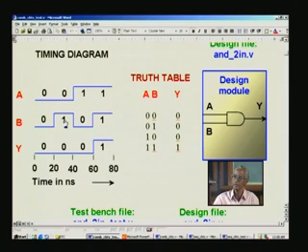Actually, if you see here, one is naturally pointing to the high state, so that is why we say it is 1. So 0, 1, and 0 is flat here at the low level. Once again a similar explanation holds good here. And at 40 nanoseconds we have made another change to 100 and 111, and this can go on depending upon how complex the circuitry is. As far as this is concerned, you can deem it to be a complete test if you have tested all these 4 combinations here.